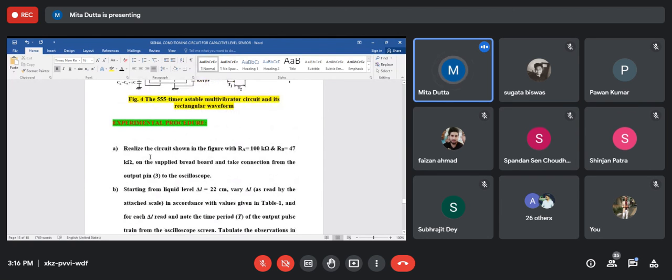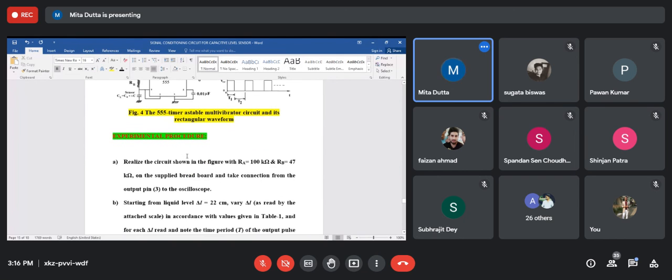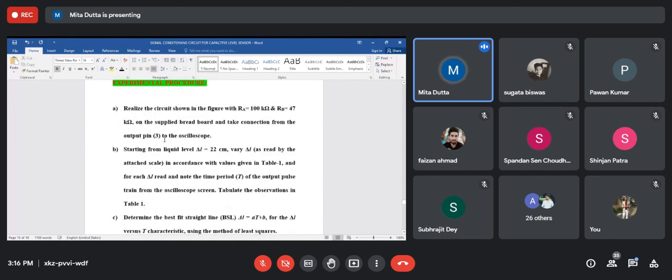So in the experimental procedure, what we are going to do, here we have to use RA 100 kilo ohm and RB 47 kilo ohm. And on a breadboard or a Vero board, we make connections like this, and pin 3 to the oscilloscope.